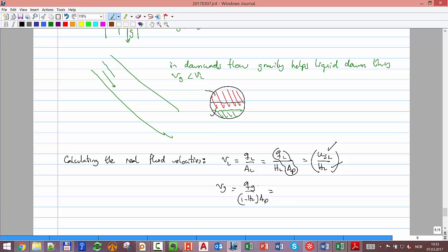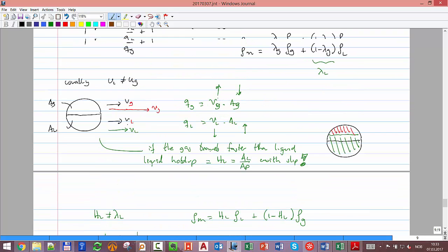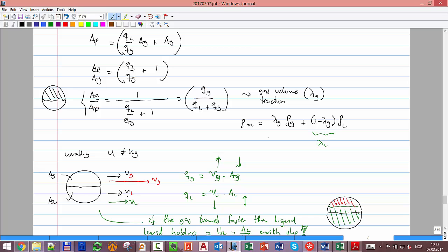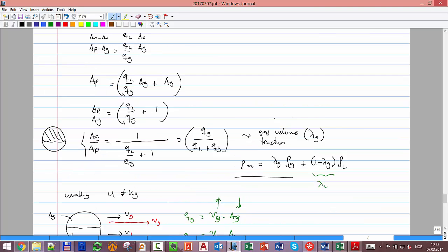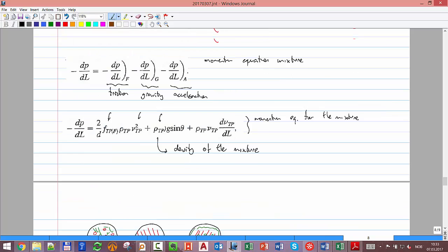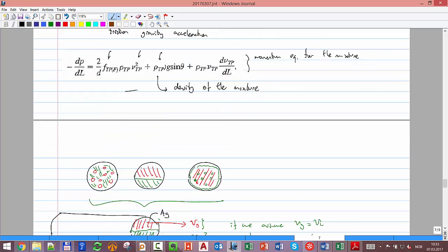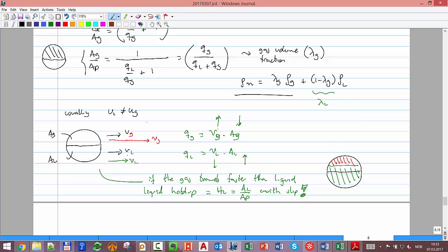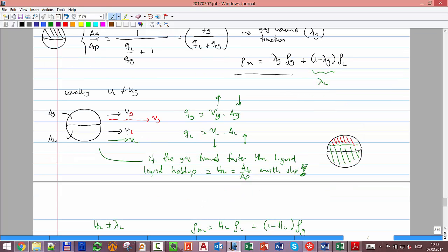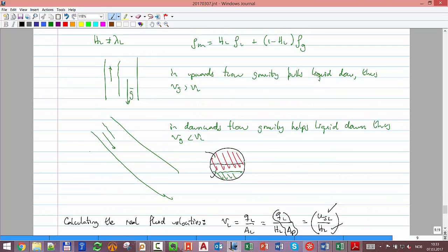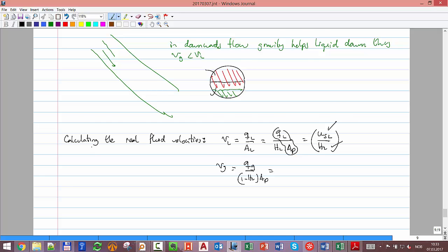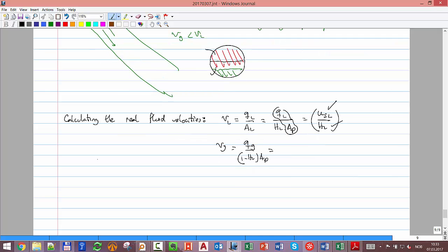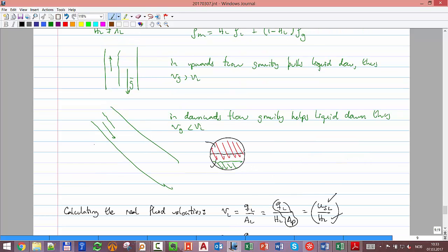The thing is that you have some equations that relate each one of them, but remember, they usually go away. If I have no slip, I can assume homogeneous flow and use straight away that equation and that equation. If I have slip, then I have to use something more complicated. I have to calculate the holdup, and I have to look at the liquid phase, for example, separately.